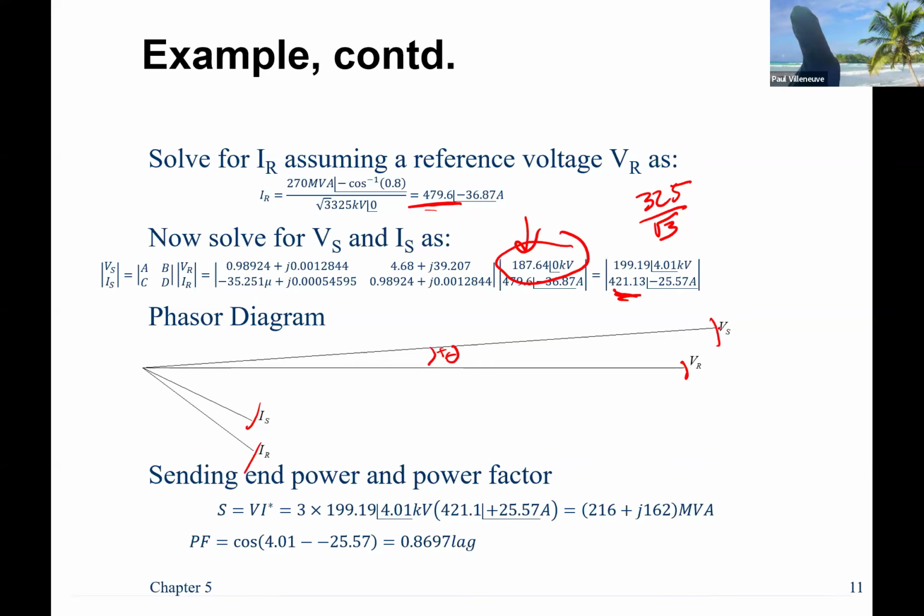Okay? So I can look at this, and that's why I said beginning of the semester, I said knowing magnitudes and angles is really important because I can pretty well predict where power flows are going to be just drawing these phasor diagrams. The currents don't matter all that much, other than to say they're both lagging power factors. Most of the time when you look at current of the utility system, they really only care about the magnitudes and nothing else. Okay?